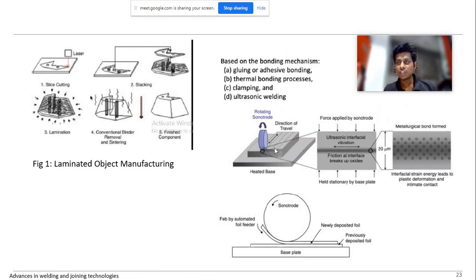Similarly, nowadays the usage of friction stir welding is also picking up the pace. One of the major advantages of friction stir and solid state welding is that dissimilar materials can be joined, right? So you can even achieve functionally graded materials. Functionally graded material means we can change the properties of the material along the component, either compositionally, so that we can achieve the required application.